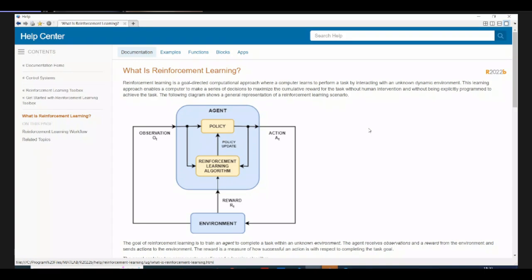I will have a 2 degree of freedom arm. With different lengths we can have, but let me consider equal. Equal lengths. So L1 and L2 are the same. 1 meter, 1 meter, total 2 meters. Now, if this is 1 meter, it is going to attain only this part. This is the radius, 2 meters to this part.